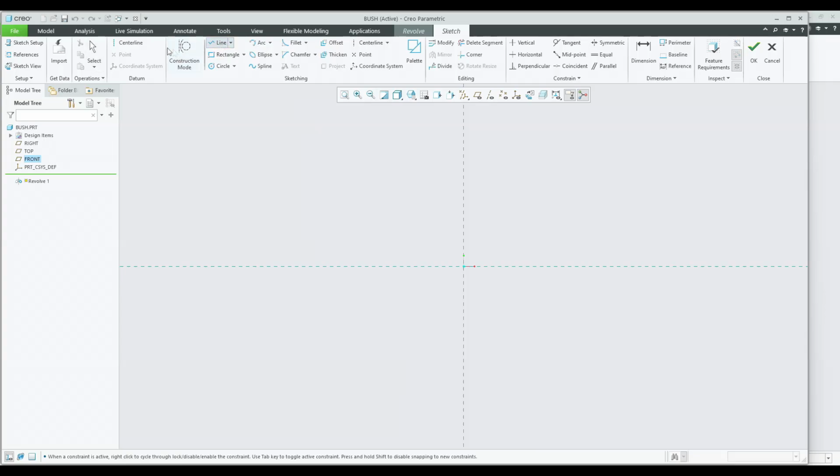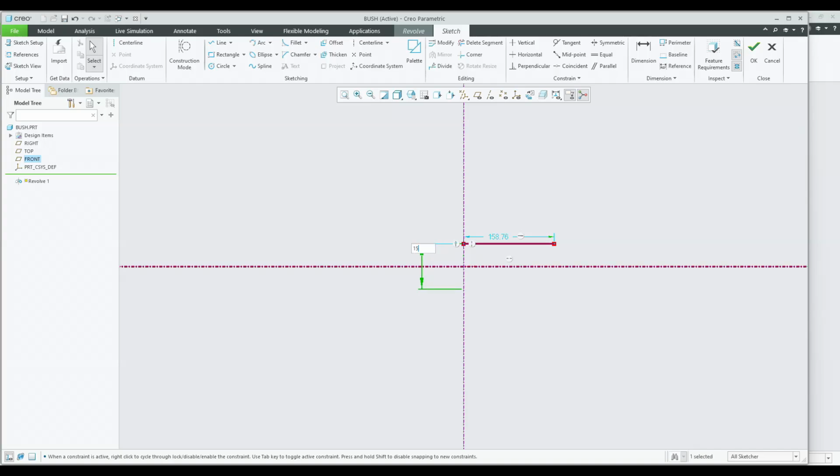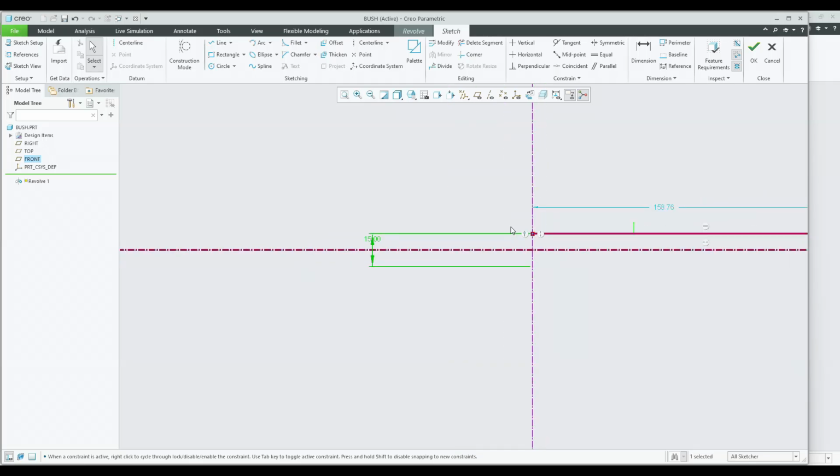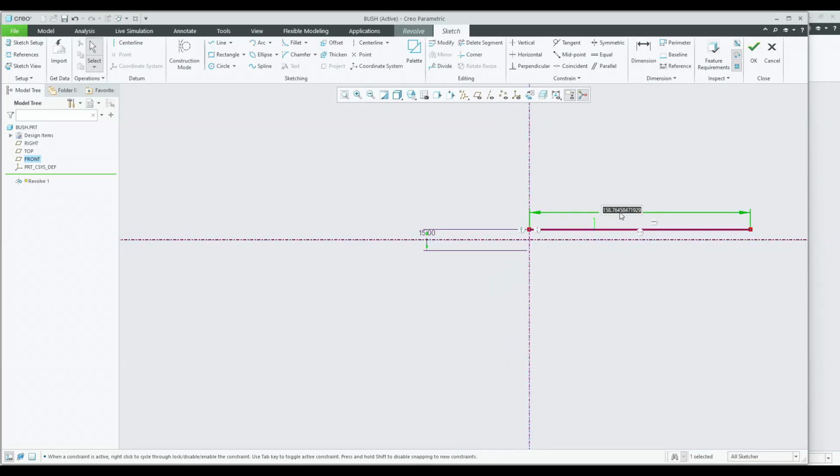Here we are already aware of the diameters of the pin which we have created right away, so we can directly define the bush on its own dimensions. The internal diameter of the bush will always equal the 15 mm which we have created for the hole as well as the pin in this area. And the length will be considered as 0.8 into D.